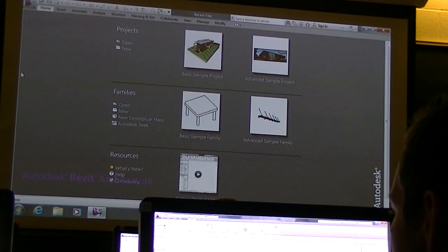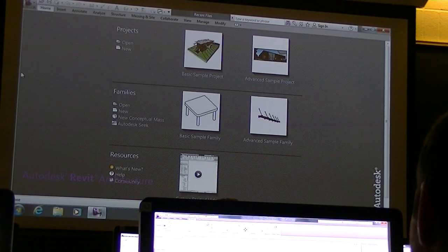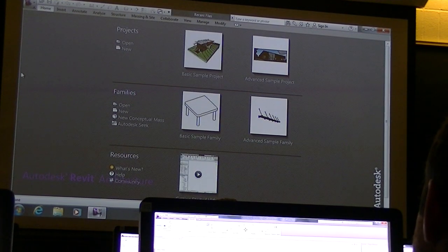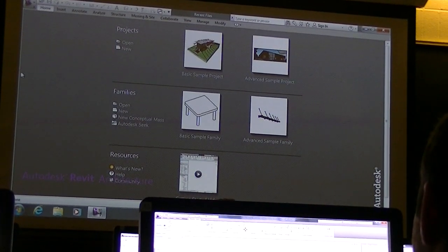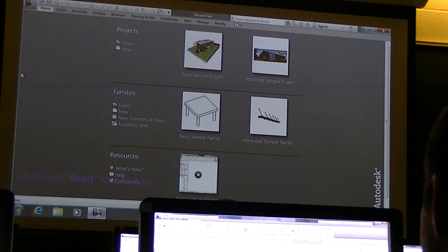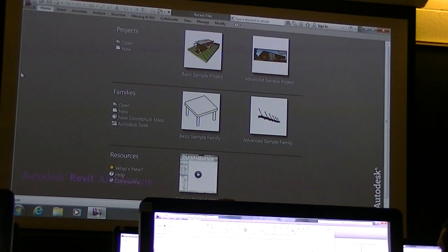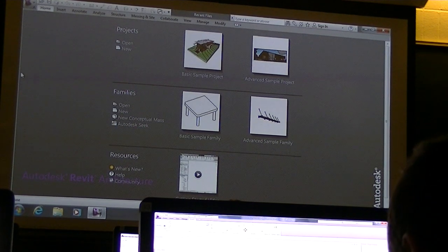You'll probably notice, if you've used Rhino, that terminology is in there, and we're going to see that when we start to divide a surface. There are U divisions and V divisions. If you were to look at a surface, U is essentially considered the X on that surface, V is the Y, and surface normal is perpendicular out from that point. So that yellow, that little orange, should be showing you a perpendicular to surface normal as your Z-axis.